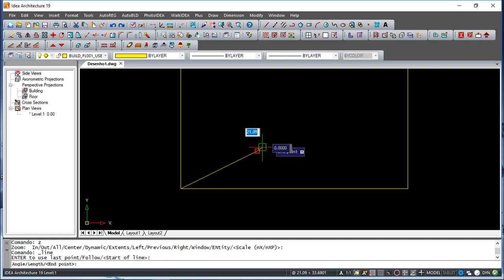We can do another thing now. I will pick this point here, and I can still use the Cartesian mode, but this time instead of a number followed by another number, I say again 100, and now 30. But if I say this now, it will take the origin again as the reference.